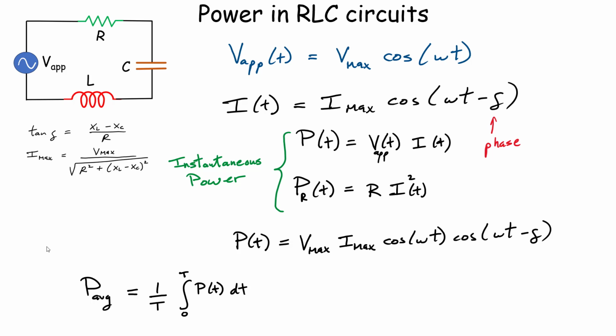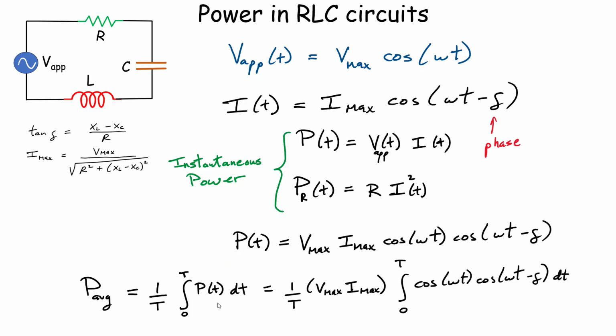So now you take my expression for that instantaneous power and simply substitute it right here into this expression. This is going to be a long, messy expression, but no problem. You just substitute that in there. And now we're left with taking out the constant terms, bringing them outside of the integral. That's what I've done over here with Vmax and Imax. And now I'm left to evaluate this integral between those limits of integration.